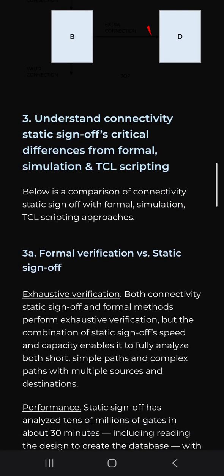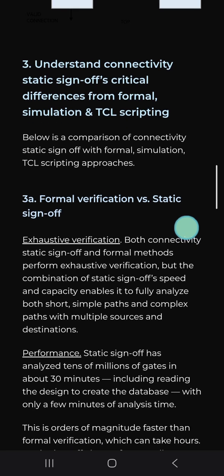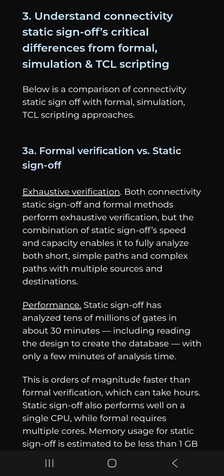3. Understand connectivity static sign-off's critical differences from formal verification, simulation, and TCL scripting. Below is a comparison of connectivity static sign-off with formal verification, simulation, and TCL scripting approaches. 3A. Formal verification and static sign-off.